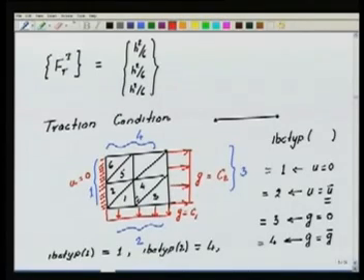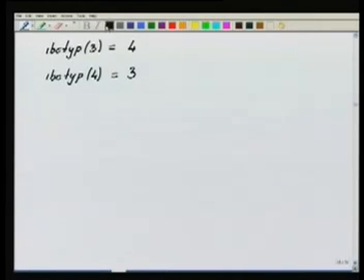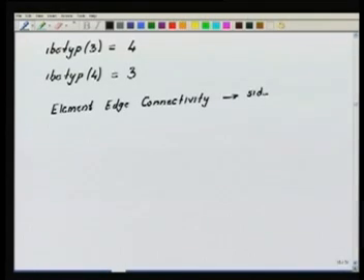So what I do is, while we are making the mesh, we make essentially a neighborhood information for the edges of the elements. So we call it element edge connectivity, and we'll give it a name. We'll say side underscore neighbor. And this will have, for all the elements, that is, there are NEL elements in the mesh, and for the three sides of the element.